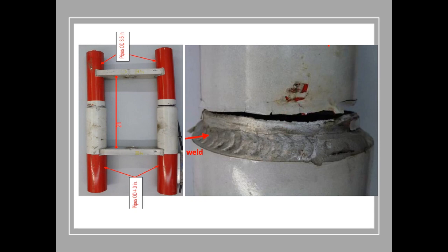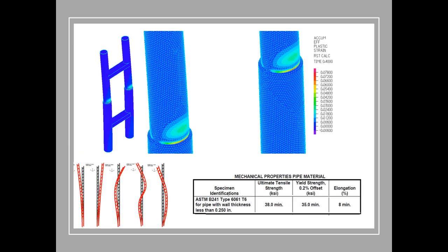To demonstrate that the gate section was not designed to sustain this level of wind load, a three-dimensional finite element model was developed using 0.2-inch 3-node shell elements, and the analysis was undertaken for wind load of 70 miles per hour. The weld material was also represented in the model. The analysis demonstrated that the plastic strain reached the ultimate value at the row of elements right above the weld, which is approximately 0.15 to 0.20 inches from the weld. The ultimate plastic strain reached was an indication of failure.